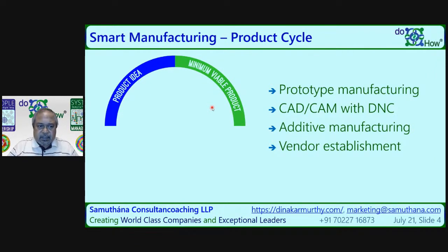So that's something where one could automate, provided the fatigue load of the component is understood. That is the next thing which is possible. And here, apart from additive manufacturing or 3D printing, there are also possibilities where you could do galvanic printing. That is not 3D printing, where you deposit material one on top of the other using the electrolytic process. That's again additive manufacturing, but it's a different technology.